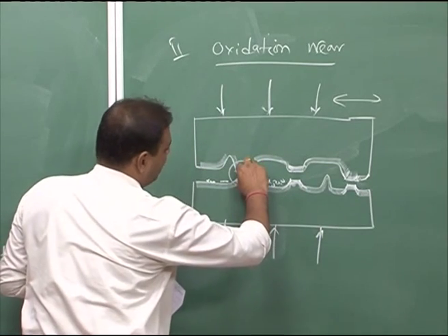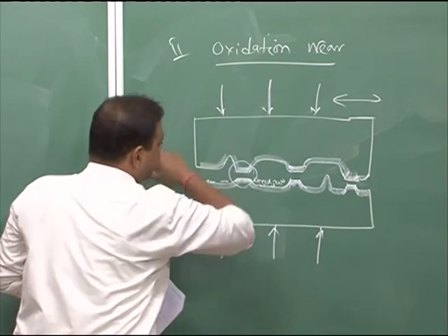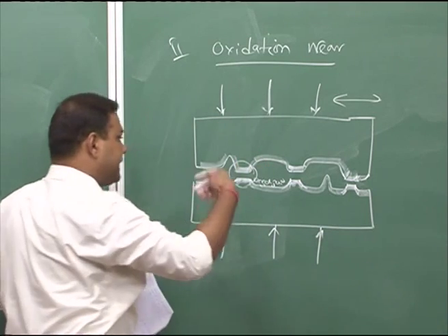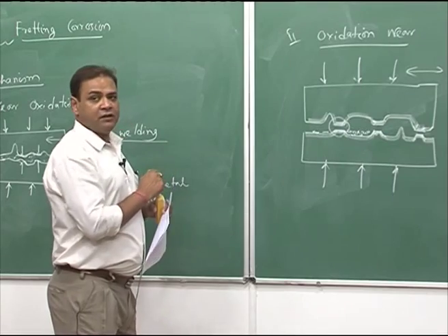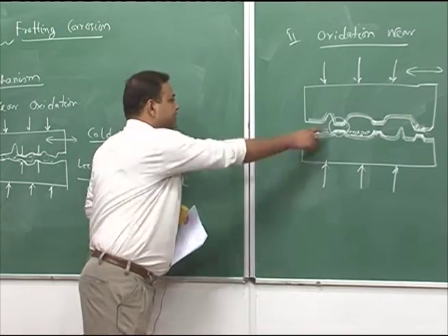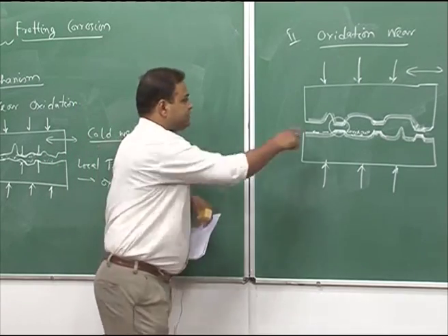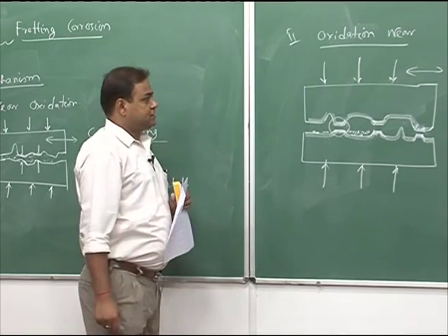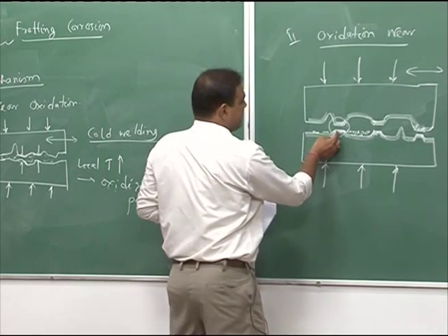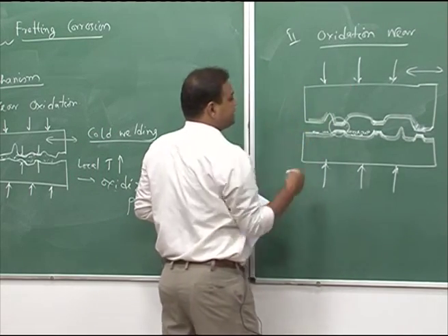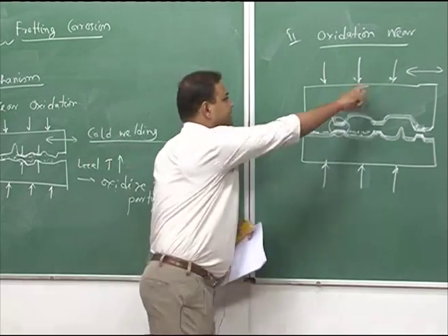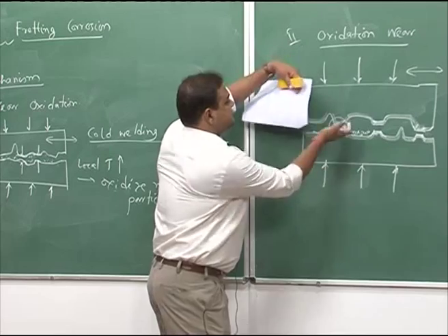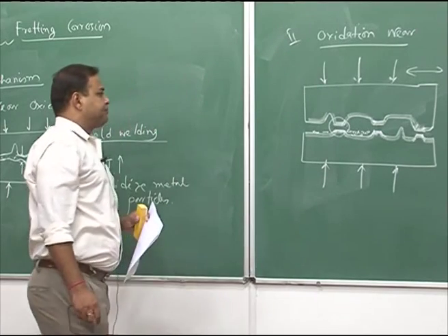They will come into contact again, and there will be relative movement. The oxide surface would get dislodged again, fresh metal is exposed to the environment, and then this fresh metal surface would get further oxidized. So, that means oxidation is happening, and the wear is basically removing the oxide layer at the contact point because of this relative movement, and always the system is under pressure.